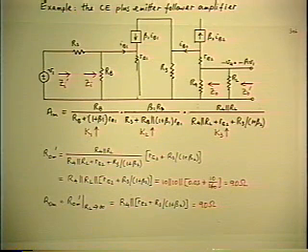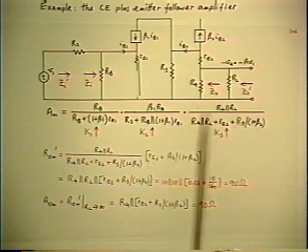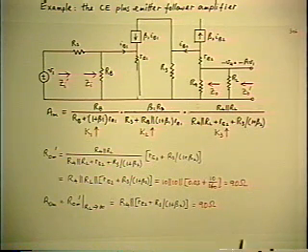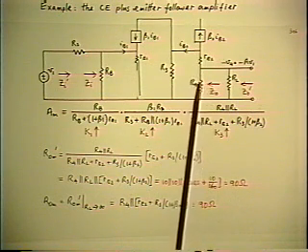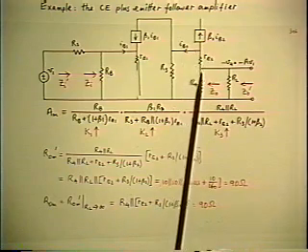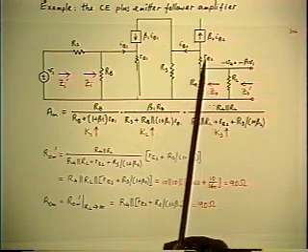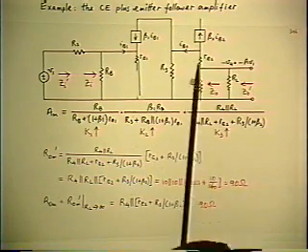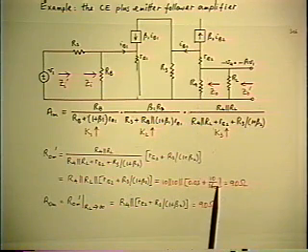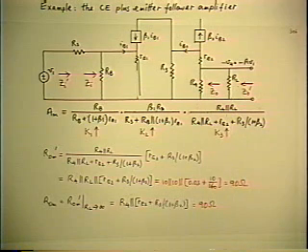Of course, the result is what you expect from an emitter follower. That's one of the reasons for using an emitter follower, to give you a low output impedance. And you see, the reason it's low is because of its reflection property. Whatever impedance there is in the base appears in the emitter divided down by the 1 plus beta. Add that to the RE that's there anyway, and that path has a much lower impedance than the external load itself does.